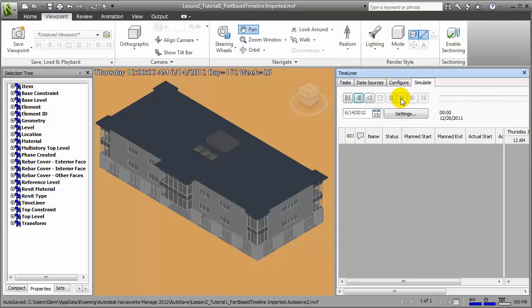A more efficient strategy that's often employed to improve the schedule is to subdivide the building into separate regions. Then to plan the work with crews finishing up their tasks in a specific area and then moving on to the next area, freeing up the first area for another crew to begin the subsequent tasks. By layering the tasks of several different crews and setting up parallel workflows that track each other, we can often greatly improve the overall schedule by reducing the amount of waiting for prior tasks to be completed.